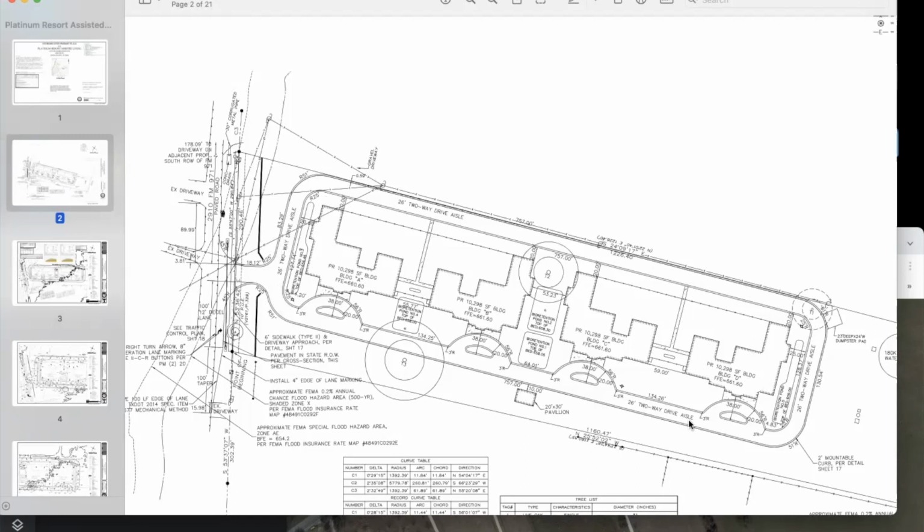So just for cost for y'all, it's a lot of road. But I'm at 200 grand for the asphalt part, and then the concrete curb around both sides are about 80,000. So 280 for this road. And again, it's really long. I don't remember how long it is, but just for kind of rough numbers for y'all.